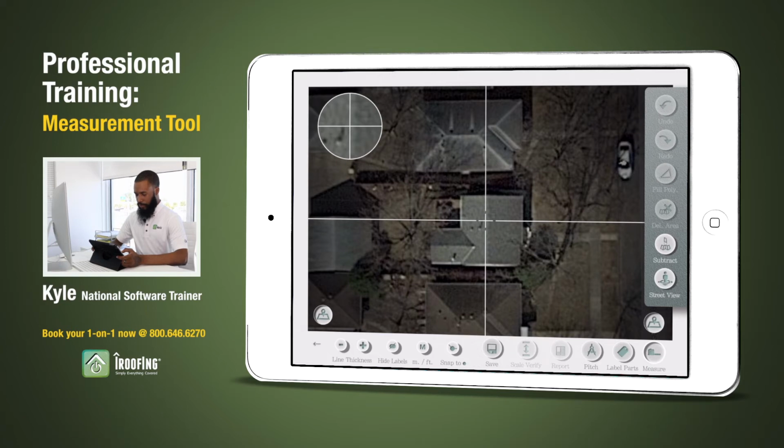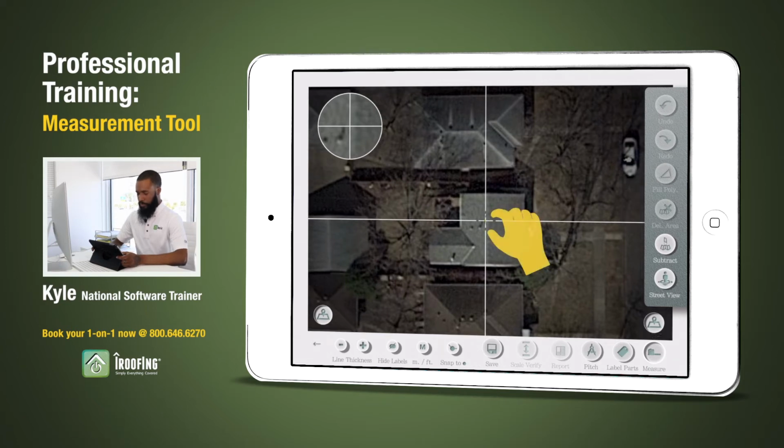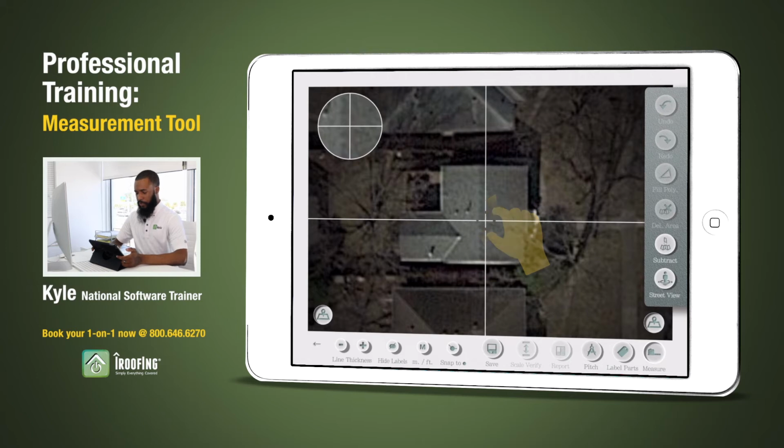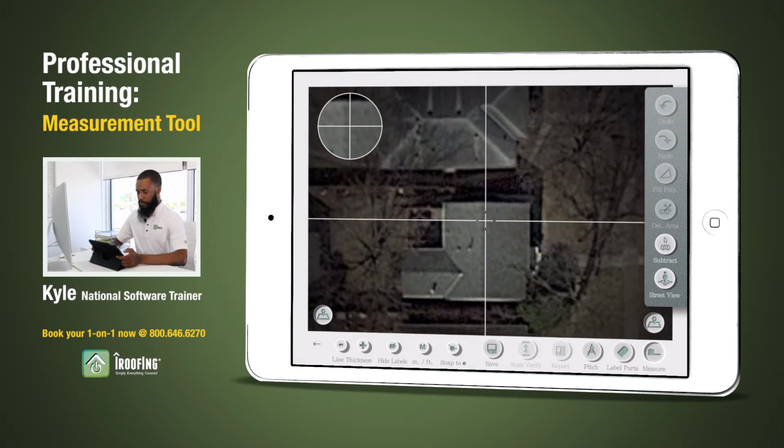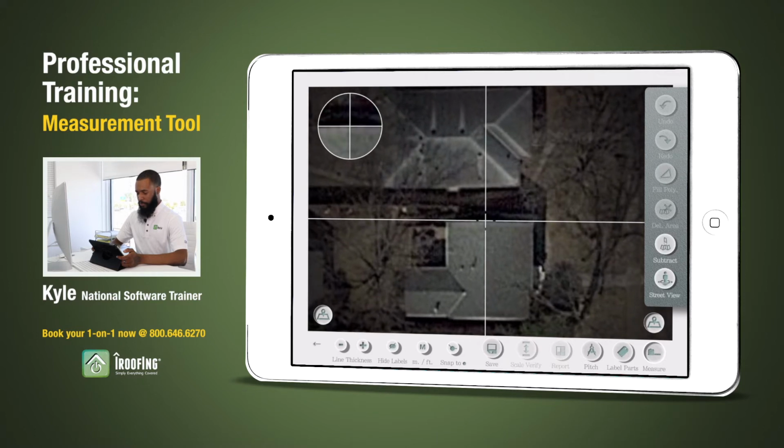So to begin our measurement, we'll first take our crosshair, zoom in a little bit closer by spreading two fingers apart on the screen. We want to move our crosshair over to the top of the ridge on the center of the roof. And we want the line for our crosshair to be right on the outside of our rakes up at the top. We will then hit the marker button, which is directly above your measure button in the bottom right corner, or in the exact opposite corner of the screen. When you hit that button, you'll see a red dot appear underneath your crosshair.